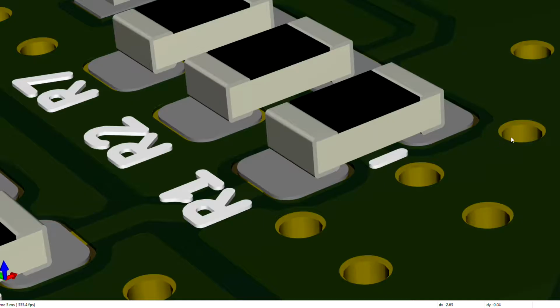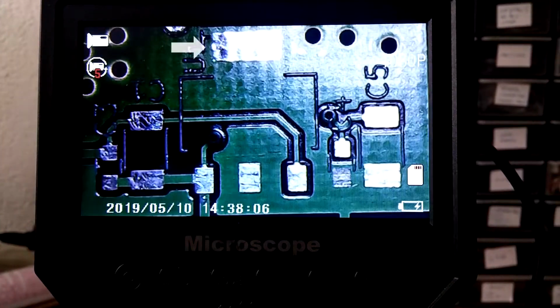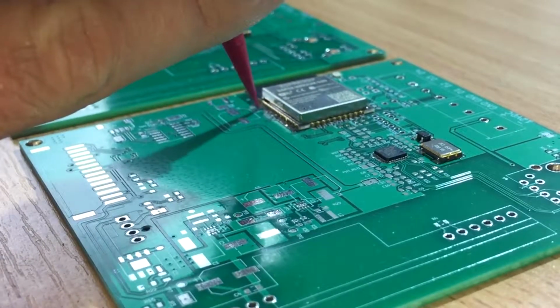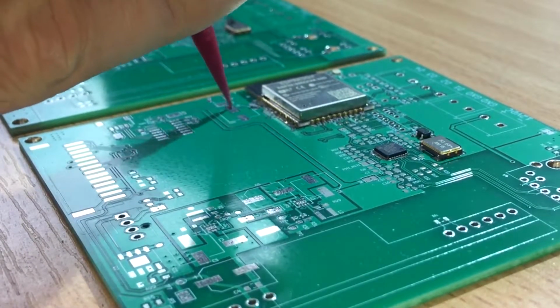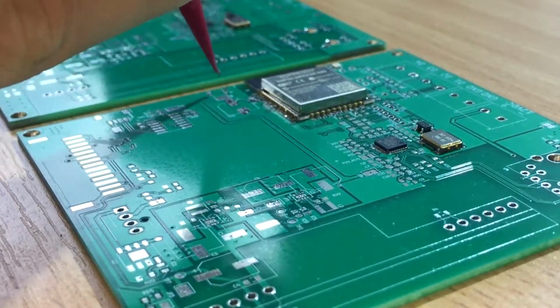Surface mount technology was developed to battle one of the biggest disadvantages of through-the-hole technology, and that is its size. Components are mounted directly onto the surface of a PCB and soldered on their pads. SMT allows higher component density, lower cost and faster production time. But take into consideration that smaller size also means a lower power rating.